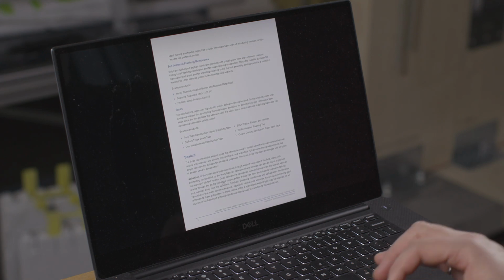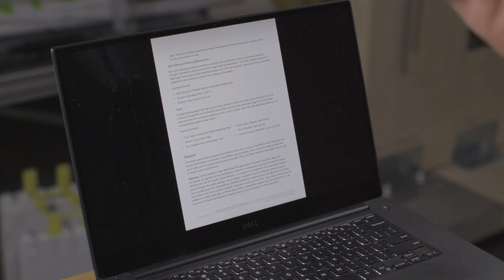Next one is sealants. With sealants, where you're using sealants around window perimeters to seal different transitions, you've got to find a sealant that's going to stick to that substrate. House wraps, which a lot of sealants tie into, are notoriously hard to seal to, and therefore special sealants that have been tailored for house wraps are critical to use. What we're looking for here is cohesive adhesion to that substrate. You can often find this from the manufacturer, but it's often easy to get some of these sealants that you could be using, and we recommend a starting point here, and then try them out on your substrate. Build that mock-up, test them out, do the pull testing yourself.